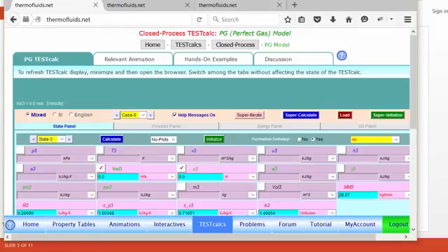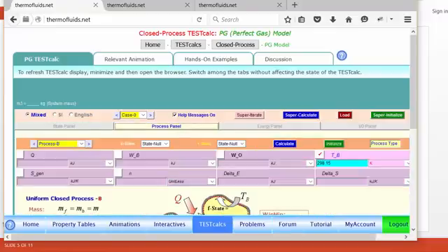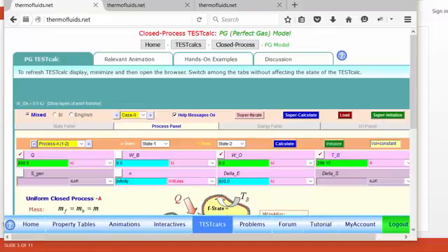So we go back and try to find state 3, where pressure doesn't change, so pressure is the same, mass doesn't change, and we know enthalpy H3 equals H1 plus 800, that was the heat transfer, divided by mass, which is M1 I can put, and that gives us the temperature, verified. We go to the process panel, and process B, remember process A was our state 1 to state 2 constant volume process.